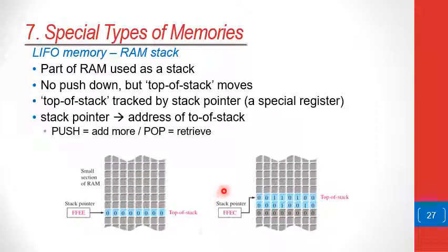So adding data into the stack, we are simply saying we are pushing it. We use the word push to add more data into the stack. When data has been retrieved out of the stack, the stack pointer now starts to decrement. It decreases and moves to the next point, and that piece of data is considered to have been popped out of the stack, or retrieved. And so in this case, the data that was put finally into the stack, which was the last to come in, will be the first one to be read out, because the stack pointer will always point to it.